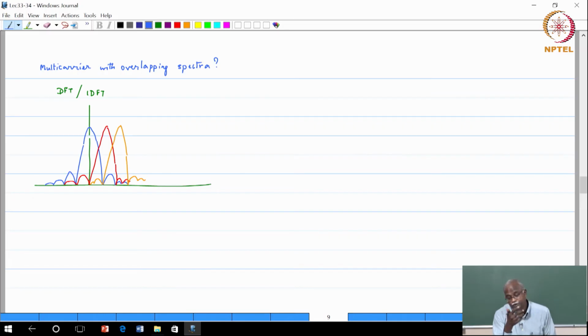You can visualize the DFT as a filter bank that was splitting channels, and you can think of the IDFT as a multi-carrier system where the information that is on the blue and the red and the orange actually gets combined into a single signal. So actually the multi-carrier is known to us in the OFDM, and do these things maintain orthogonality?